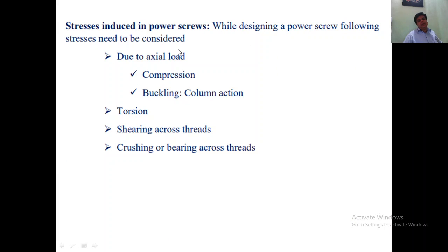Coming to the main part now, designing of the power screws, we have to calculate the stresses induced in the power screw's material. Power screws, as you know, are subjected to axial load, maybe compression load, and since the length of the power screws is significant, they are subjected to buckling also. What you learned in columns in mechanics of materials, that buckling concept has to be calculated for the power screws.